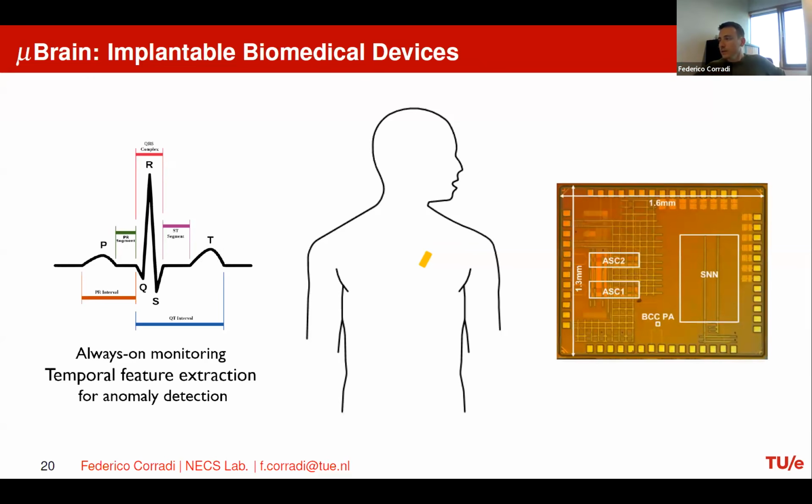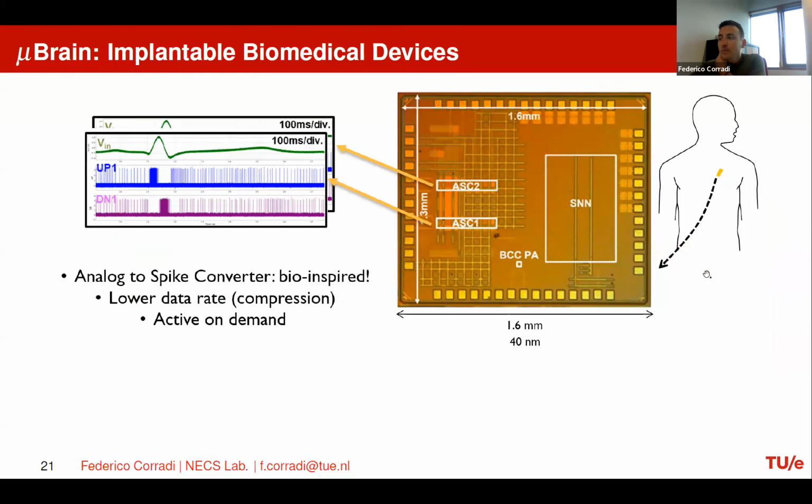behaviors. And so what we did, we resynthesized the microbrain architecture, and now we did it with an even smaller network. We only used 100 neurons, fully recurrent, because that's enough for us to solve this temporal task. And still, it is a 40 nanometer chip with 1.6 square millimeters. As you can see, most of the area is actually empty, is filler.